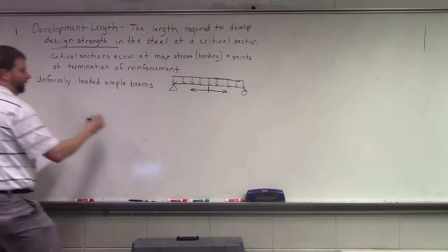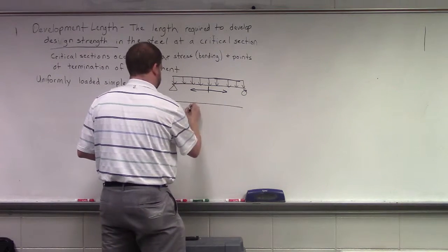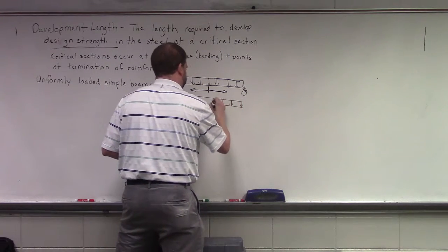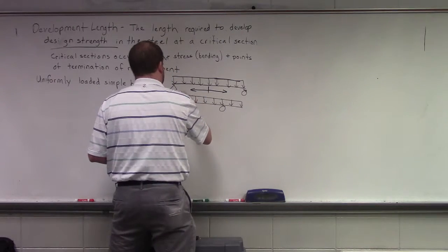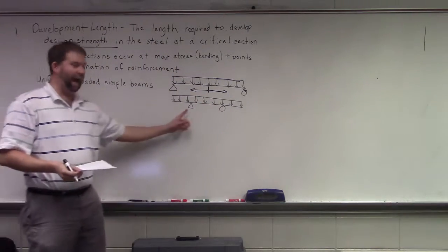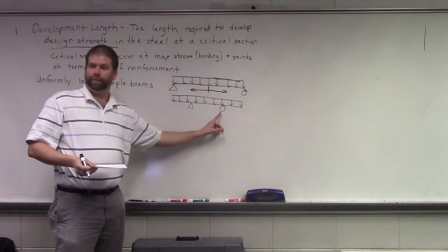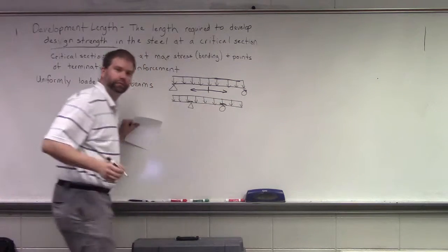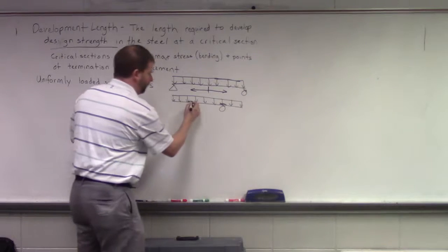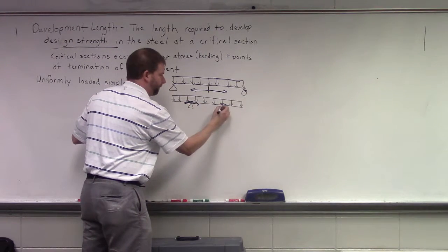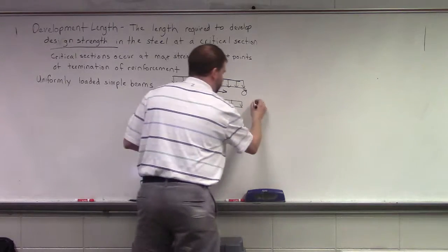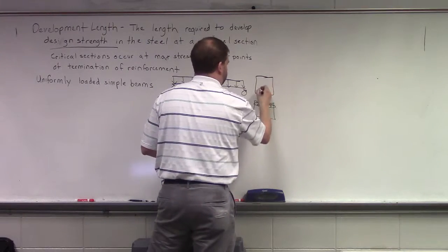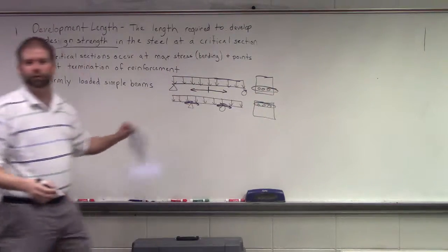We also have to keep in mind, remember we also looked at beams where we had cantilevers. Where we had a cantilevered section. And do you remember what happened over the supports? Yep, so we would actually have bending in the top of the beams, right? So here we need to check what length we need to develop over these sections in our top face. Okay, we're looking at reinforcing in the top. Here we're looking at reinforcing in the bottom.